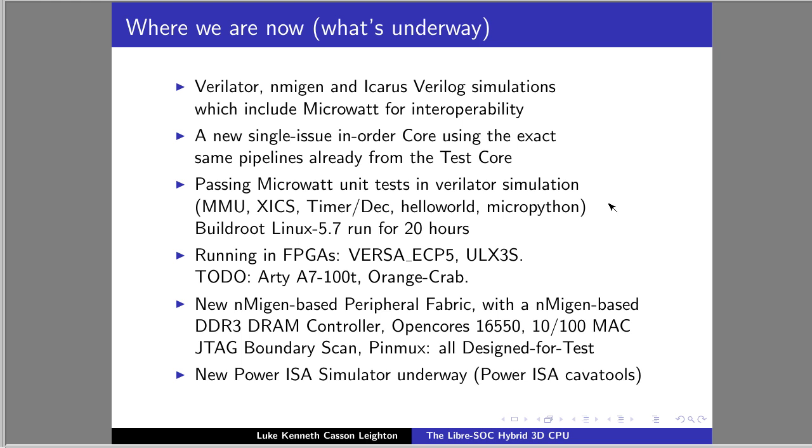It's actually because the different pipelines complete at different times. So the multiply takes 3 cycles, logical and the ALU take 2 cycles. Div takes, I think we've joined several combinatorial blocks together, but I think it still takes something like 64 cycles to complete, or maybe 32 cycles. So everything's different, and completes at different times.